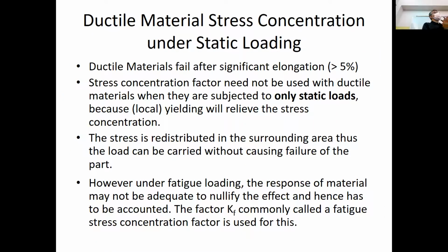Why is that? Because when you're using a ductile material, you remember it can absorb lots of energy and get into plastic deformation before failure. So even though the stress is so much elevated at that point, as it starts to deform, it will redistribute that stress into the vicinity of that point of stress concentration. And the part is not going to fail. So you're going to see some plastic deformation, but the part is not going to fail. Again, if it is ductile material and static loading.